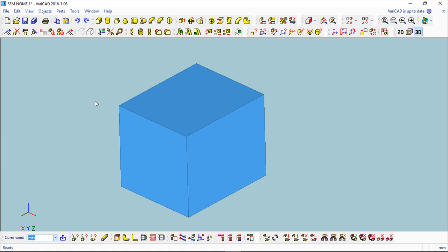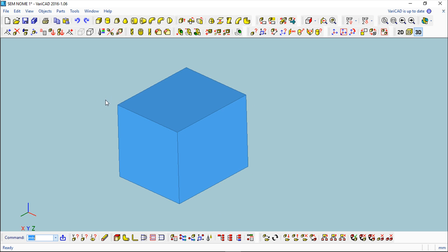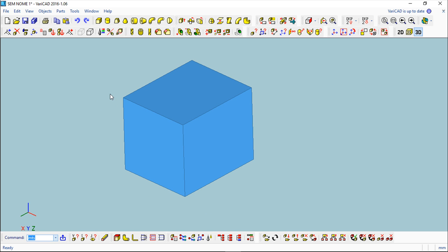Again, we will develop this topic of editing the shape and the dimensions of solids, but keep the idea that it is possible to edit the dimensions or the shape. The second way is to change the location of the solid. In this case I have just one solid, but if I want to edit the location, I will go to this function that says transformation, copy, edit constraints.